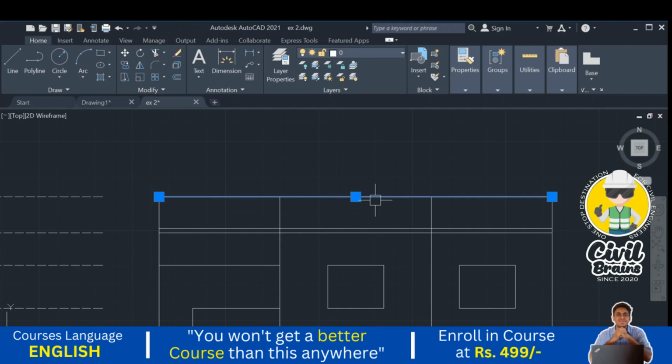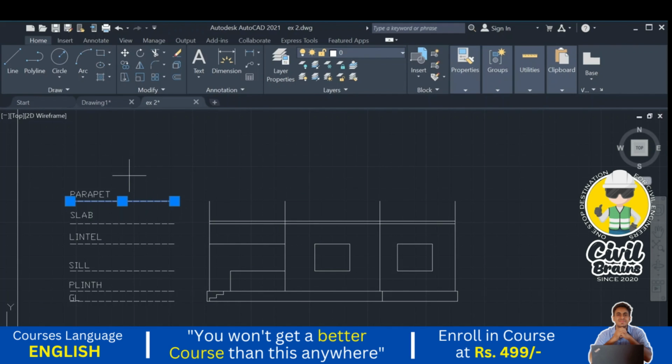Okay, so just delete this one, the level whatever we have provided is not correct. I go to the offset command, 1 meter from the top of the slab. We had considered it from the bottom of the slab, so we need to consider from the top of the slab, it is 1 meter.